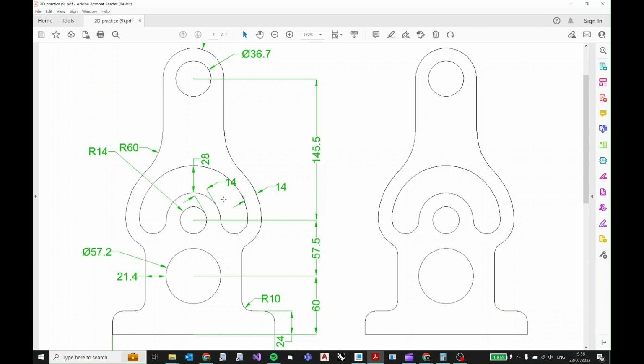Okay, you know what, we're going to make these two arcs first, and then we're going to do that one in the end, so that's going to make our calculations easier. So that brings me back over here. This arc has a thickness, and again in this case we don't know the radius of this arc, which is not shown over here, but we can still calculate it based on the fact that the distance from here to here is 14, and since the radius of this circle is 14 as well, the radial dimension for this arc is going to be 14 plus 14 equals 28.